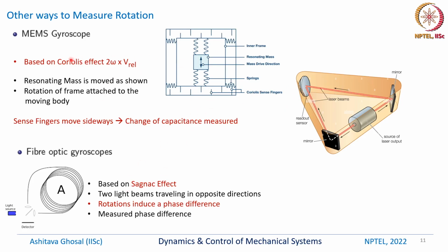Okay, this is what is called a MEMS gyroscope. This is very different from what I showed you about the rotating spinning disc. These are very small and nowadays very accurate, and they can even fit into your mobile phone. So in your mobile phone you have gyroscopes, and I will show you later, we also have accelerometers which can measure the motion of the mobile phone. Okay, we can get the acceleration and angular velocities of the body on which this is mounted.